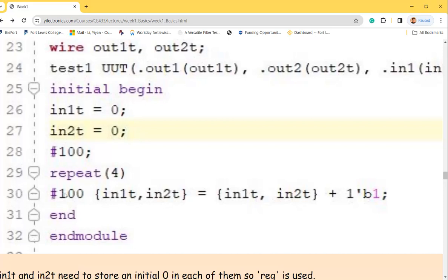So after that 100 nanosecond time delay, if you want to have anything changed to L2, when is that going to happen? So within these repeating times, this 100 nanosecond time delay, you cannot change it, right? It's going to delay no matter what. It's going to stay there for 100 nanoseconds, okay? However, after that, your L1 will be changed, but your L2 will wait for a certain amount of time before it's being changed. So how long is that time?